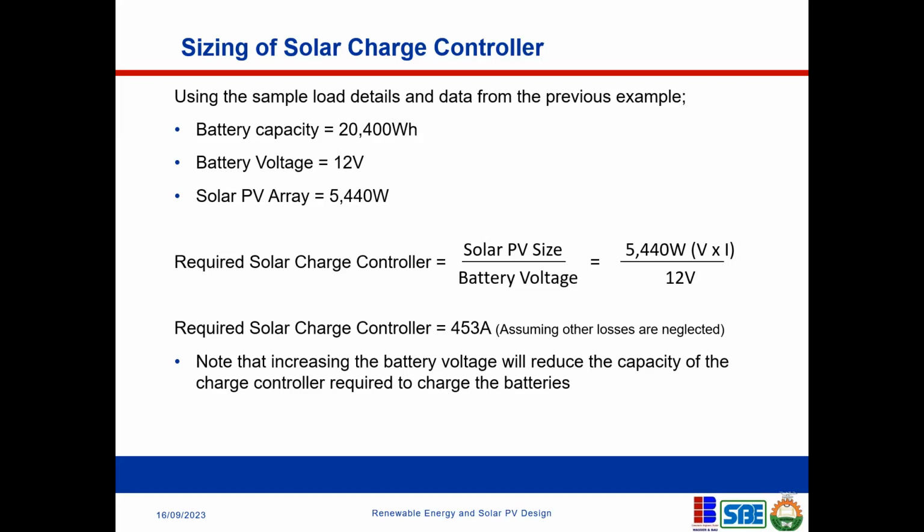But for a manufacturer to have done the design and then tells you that this is the voltage range to which the equipment can work, you have to stick to that voltage range. So if you have gone to the market and procured a high voltage inverter, you need to connect your panels in series to get that voltage that you need to input into that inverter. Whether it is safe or not, I am not a safety certifying agent to say, okay, it is safe or not.